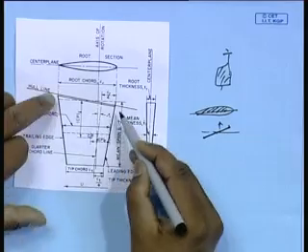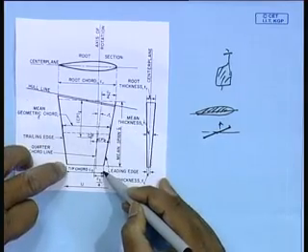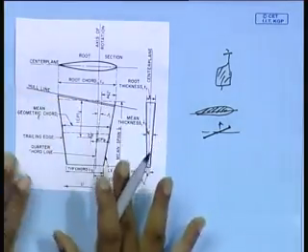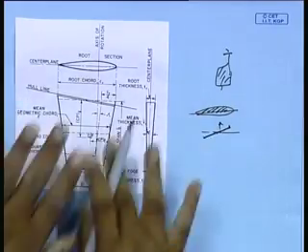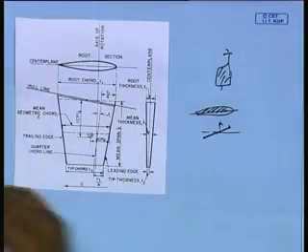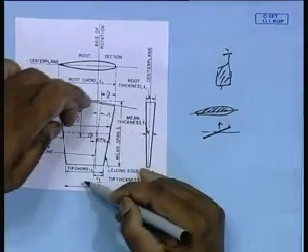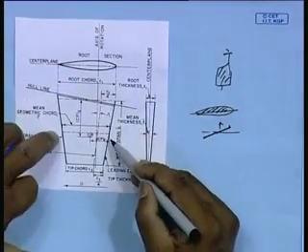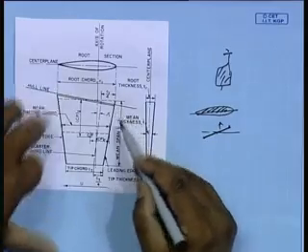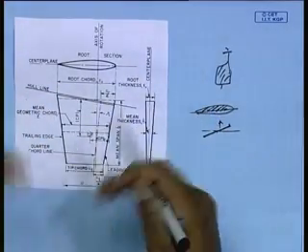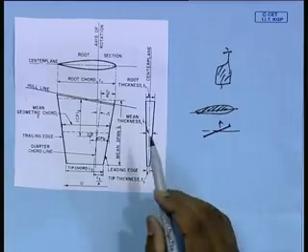This is the root section, tip section, the tip chord, this is the sweep angle, etc. We plotted that yesterday in terms of the important parameters, as I mentioned before: aspect ratio, the effective aspect ratio, because this is not exactly the same. So you can take the mean line, or span squared by area. If you call this the span and this the area, span squared by area becomes the effective aspect ratio.